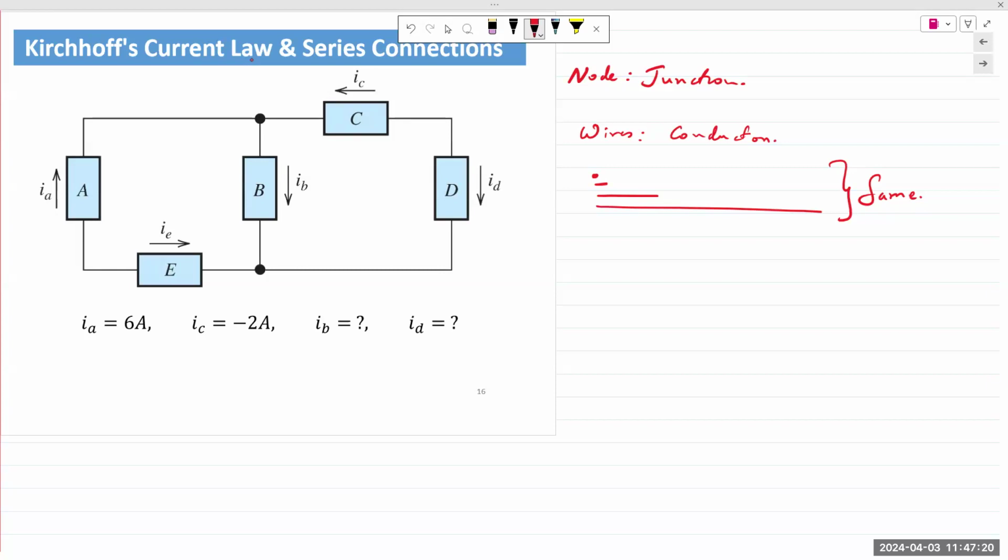So coming back to the example, you have a 100-foot long cable. If you plug into the wall and you measure the voltage at the other end, you would expect it to be 120. It might drop to like 119 perhaps, but even that's not a significant drop. The resistance of that 100-foot long cable is probably 1 or 2 ohms or less. A wire has some resistance. It has some inductance. It also has capacitance. So any wire, for instance, the USB cable, the HDMI cable, they all have resistance, inductance, and capacitance.